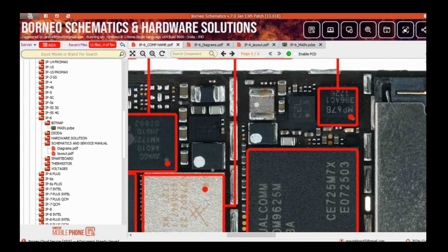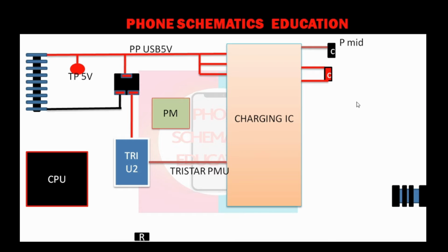Now get back to the right. Now next, I will tell you about this coil. I will show you just this coil. This line goes to VCC, the main always-on voltage, like VPH or V system. In MediaTek you will see V system. In Qualcomm, in Android phones, you call it VPH. In iPhone you can call it VCC. This is the main voltage. This voltage goes to the audio section, network section, light, graphic, Wi-Fi, Bluetooth, most of the sections, right? So this is the main voltage.